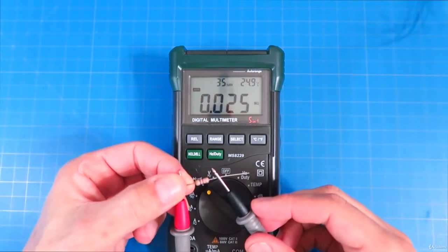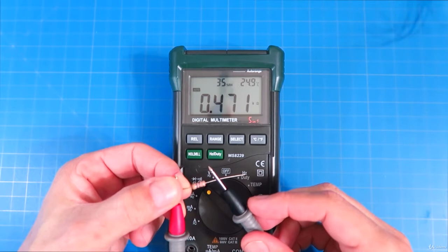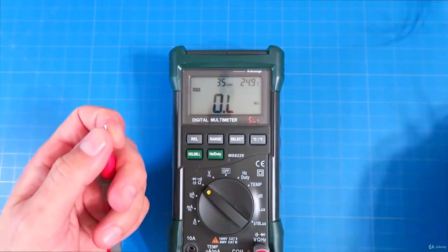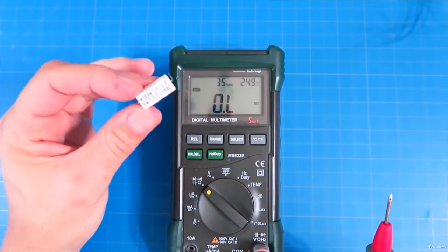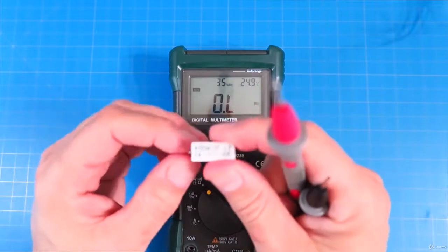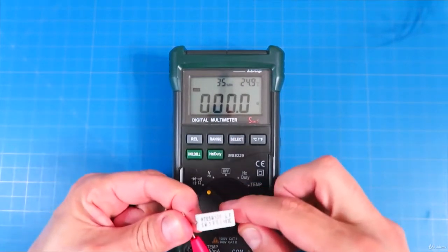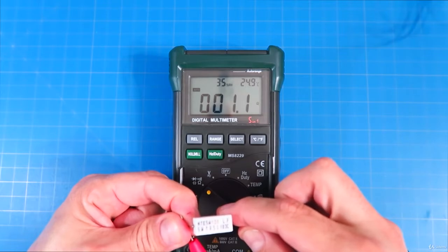We touch both leads, and it's tracking and figuring out, and it says 0.470 K, or 470 ohms. So 0.47 K ohms or 470 ohms. Okay, that's 470 ohms. Great. Now let's come over and get this big guy. We believe that this is 1 ohm, but it might be 10. We're going to put it on the two leads there and see what it does. And it looks like it's 1 ohm. That's correct. So it's 1 ohm, not 10.